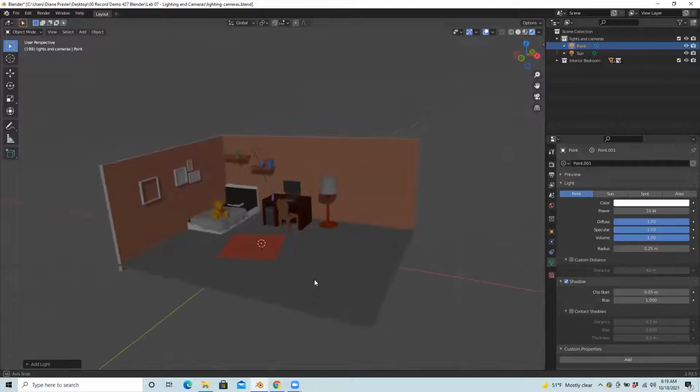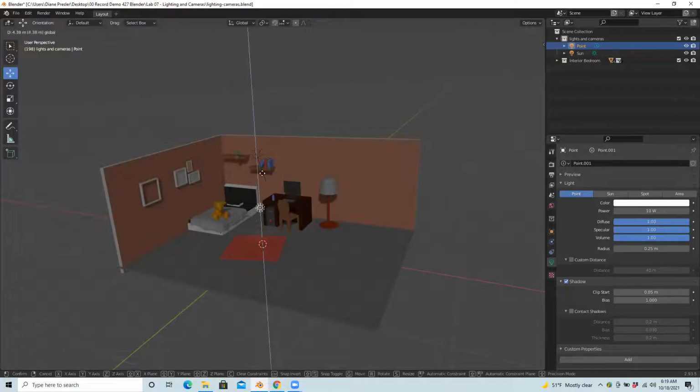And again, I want to try to simulate an overhead room light. And if you need to, you can move the sun up higher if you want to have a little bit more room for the separate lights. So you can always check that it's selected in the collection area. And then I'm going to grab my move tool, and let me grab that blue arrow and just pull straight up. It's funny, if it's close to the floor, I see a little bit of light emanating from it, but it feels somewhat weak. So let me just lift it a little bit higher in my room.